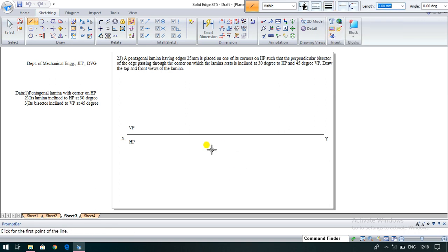The total sum of the exterior angles is 360 degree, but we require 5 sides, so each side should be 25 mm and the angle of each should be 72 degree. Start from a horizontal line. The initial side is 25 mm and the initial angle is 0 degree.